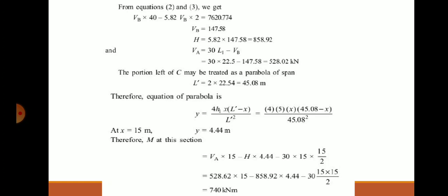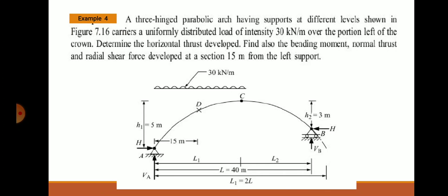So, once you know y, you can find out the moment at a section, which you did exactly similar to the symmetric circular arch, 3-hinged arch in the previous problem. So, taking moment about the section. So, here what are the forces that are coming?